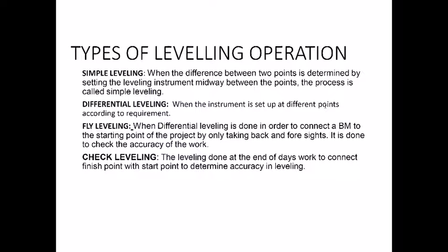Fly leveling is when you want to connect a benchmark to the starting point of your project. Like we discussed, permanent benchmarks are the ones which are set up by the government, and they might not be close to your project site. So sometimes you want to connect the benchmark to your project site, or even at your project, the reference point that you want to take is far away from the place where you want to do the work, and you want to shift the benchmark.